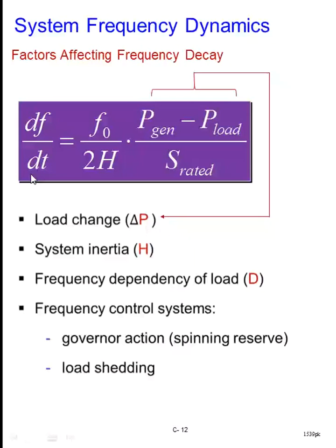In this term we have not included the load damping constant, but if you have dynamic loads, let's say induction motors as a load, they are in fact frequency dependent loads, and thus they provide a damping torque, but this is not included in the term as given here.